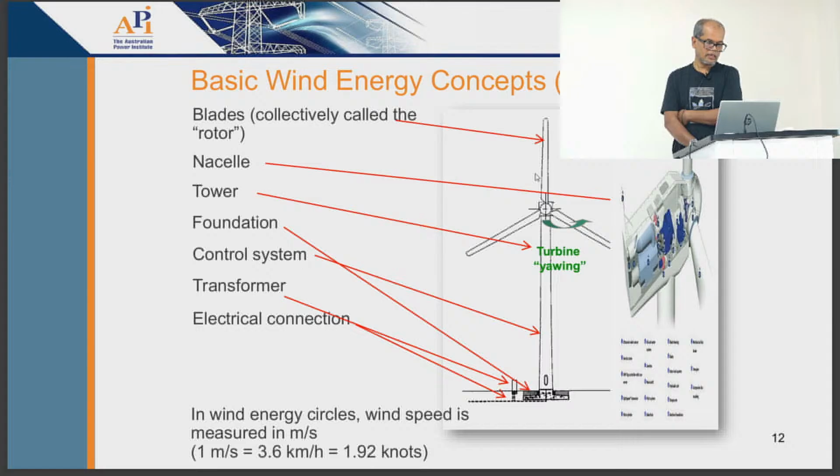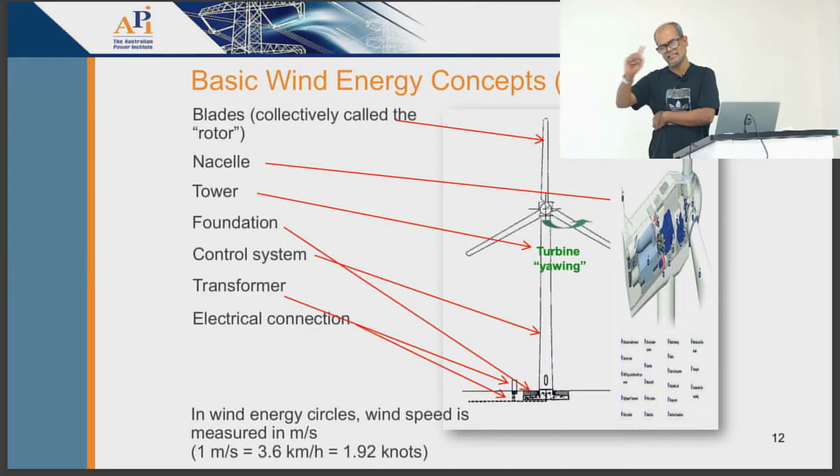So yeah, again from wind, the blade or the turbine is going to capture the energy, converting from wind to mechanical. Once it rotates, definitely there is a gearbox, because the speed of the wind is significantly lower than the speed of the generator, right? The generator speed is much higher than the wind speed. So we need a gearbox in between, same thing like a transformer.